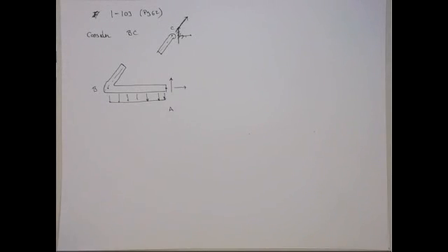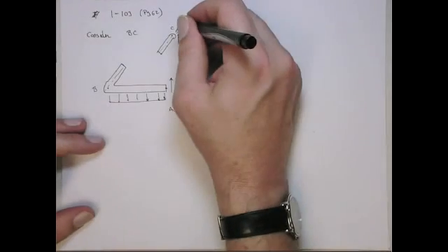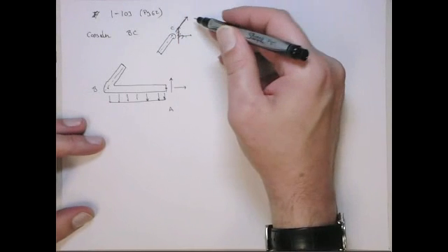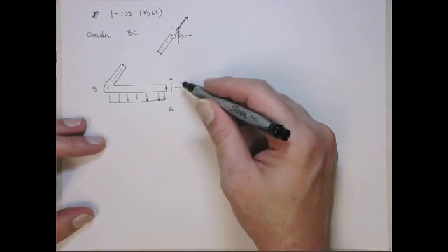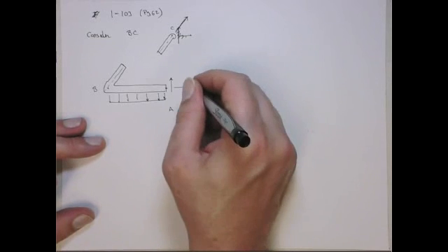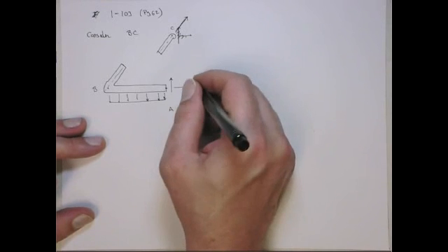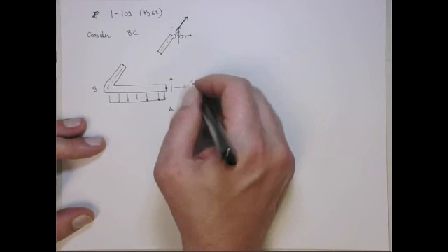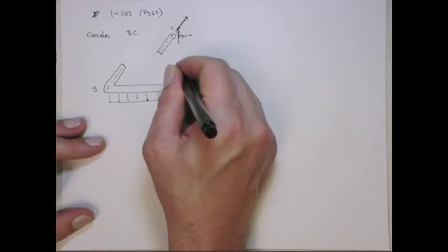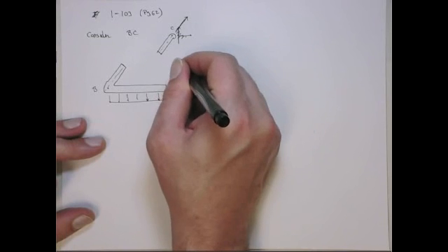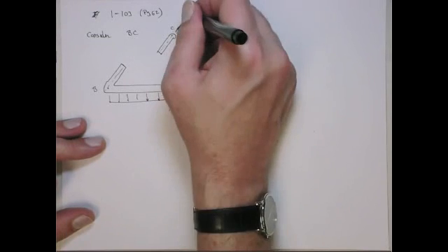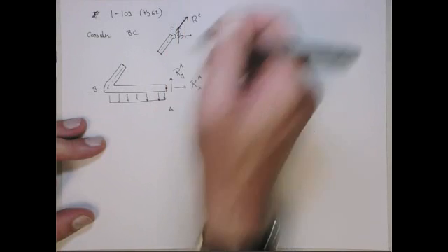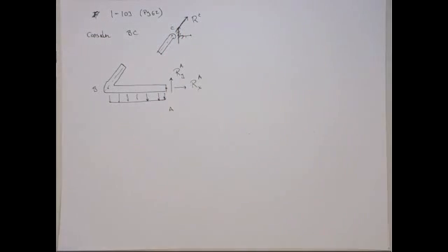All right. So in fact, once you recognize that it's a 2-force member, you know the angle, so you have the magnitude as the unknown, and then the x and y components at A. So let's call this reaction X, reaction Y at point A, and this is just going to be the reaction at C. All right, so we know the direction.